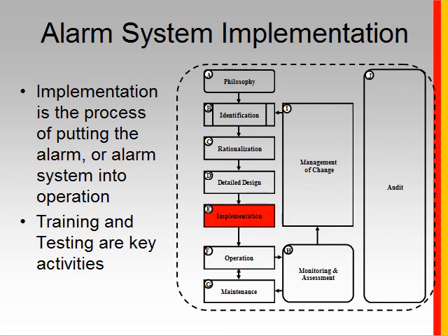Next stage is the implementation stage, and this is where you take the alarms from the design to the operation stage. Testing and training are some of the key activities here, and you can really never underestimate the importance of training to the operators, not only to help them do their job as best as they can, but to make sure that they really buy in and adopt the system.